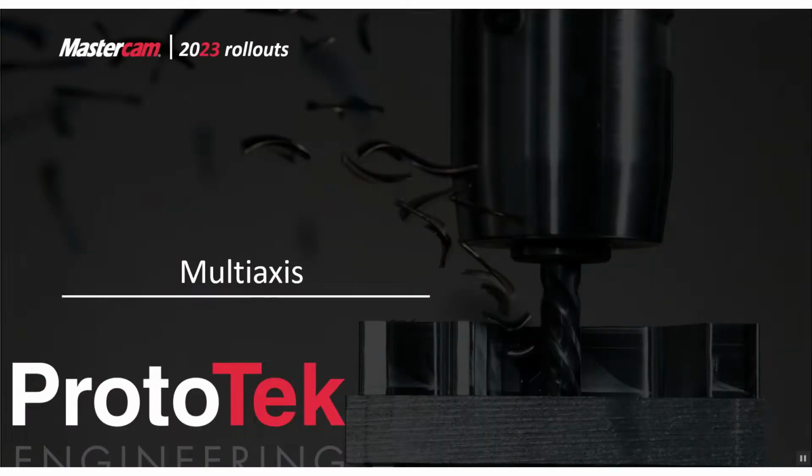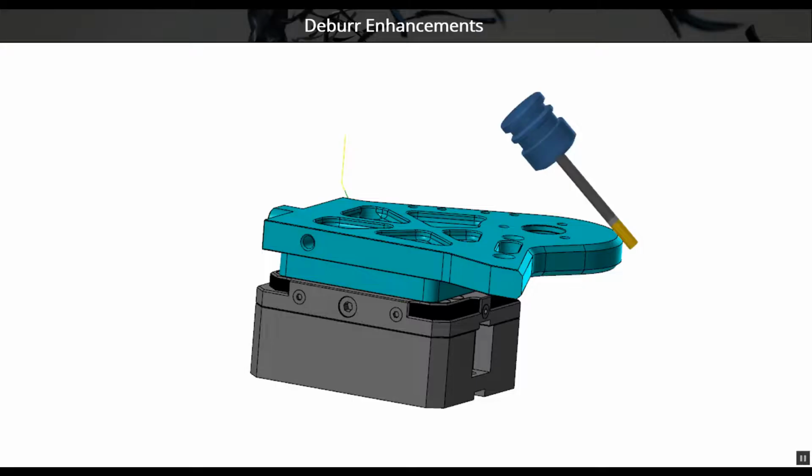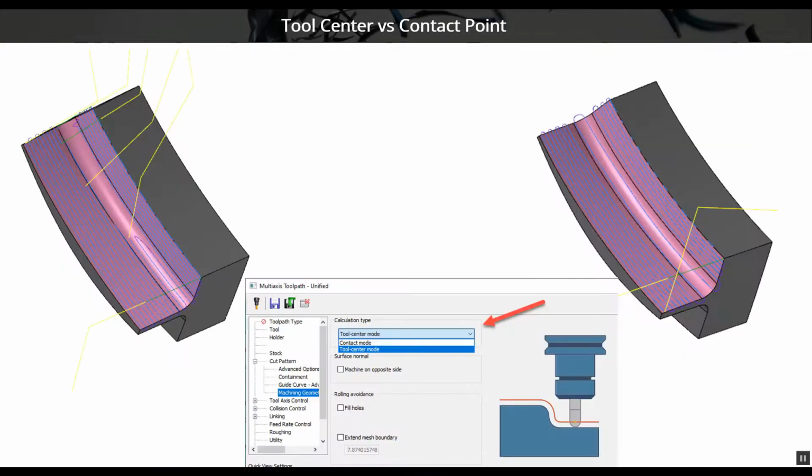Multiaxis 2023 has seen some great changes. Let's go ahead and take a look at what these changes are. Deburr has some big enhancements. Deburr can now utilize any tool essentially with a flute. So a flat end mill, a chamfer mill, a taper mill, all of them are fully supported now, where previously you only had ball and lollipop mills to use. And here's that flat end mill cutting a big old chamfer.